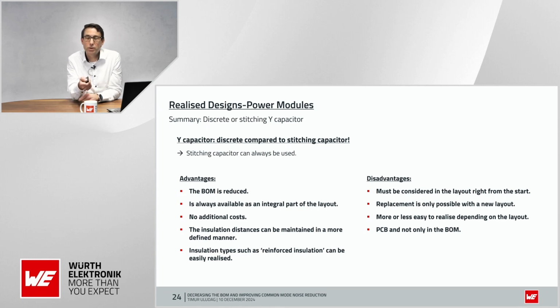For me personally, one of the biggest advantages for a stitching capacitor is this point here. With a Y capacitor that is integrated, you can easily generate a basic isolation, you can generate a reinforced isolation, and to go for a reinforced isolation with a discrete capacitor is more difficult, because then this capacitor is getting bigger, because then you are bridging the primary from the secondary side.